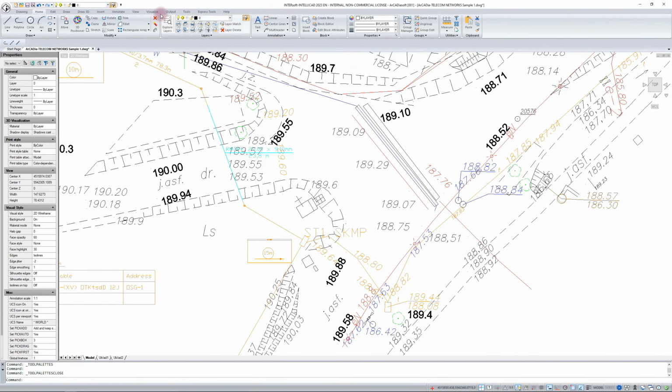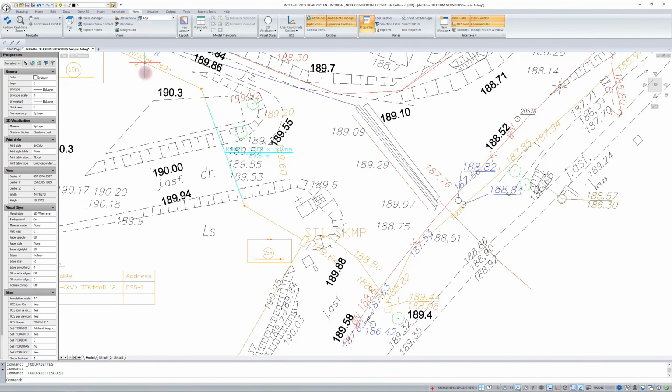So, if you see any strange marks on the document, you can then regenerate the view. I will do it via the F5, but you can just click on the pop-up message or otherwise bring up the regen option. The regen option is very useful, so please remember where this option is located.